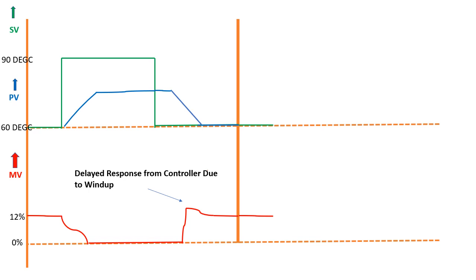The controller is supposed to be acting at this point when the set point has been changed, but it has taken this much additional time to act. Sometimes this is very critical for the process. That's why reset windup protection is always present in modern controllers.